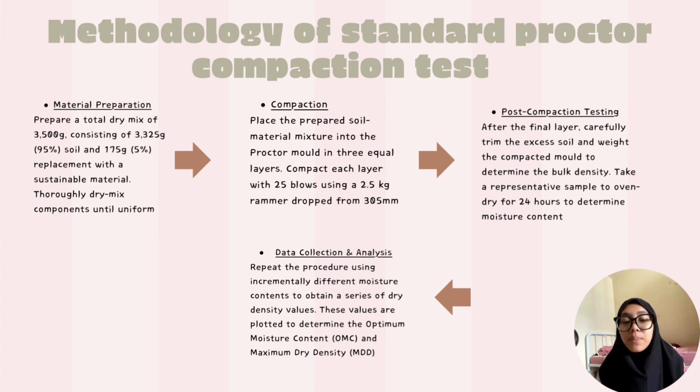Then, we repeat the procedure using incrementally different moisture content to obtain a series of dry density values. These values are plotted to determine the optimum moisture content OMC and maximum dry density MDD.